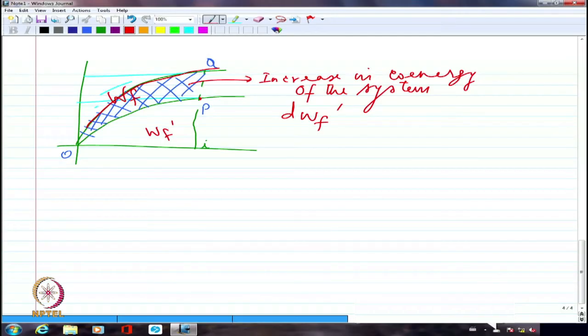Please understand. So, if I have an LC oscillation, I would say it has reached steady state very clearly, as long as the values at the beginning of the cycle and the end of the cycle are the same. Is this clear? So, with sinusoidal excitation, there is nothing like a constant value, never ever.